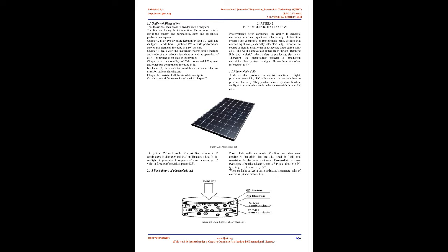But they concluded that although all the inverters in the two systems have two-stage structures, only single-stage were designed to work during most of the time, because the system efficiency can be increased. So large photovoltaic power systems should adopt series wound panels for high operating voltage and less loss. The research shows the correlation. The output power quality of one inverter of the 10 kilowatt system was analyzed.